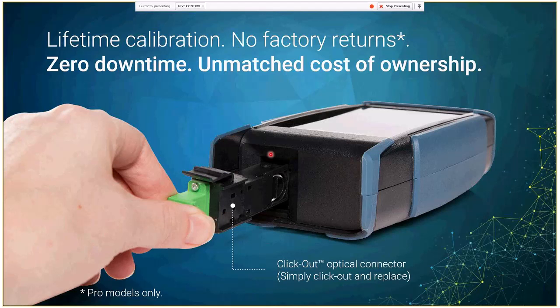So it's the first unit in the market, and this is a patent now for us, where you can remove the connector. So no more damaged connectors that need 2 weeks down, needing to be sent to the factory to replace the connector. You can replace it yourself. We even have a mode which allows you to test the connector before sending or rejecting it. So we don't want you to replace the connectors without the need of doing so. It measures the reflectance on the connector and the loss and tells you if the connector is good or bad. And you can replace the battery if you require in the future.